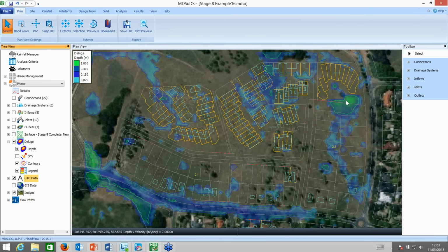So would that be an idea to put something in place like a bioretention area? If there's already some depressions there, we can do a little bit of earthwork landscaping and then maybe benefit from putting something meaningful in there right at source. So we're trying to really slow down the flows. We're trying to provide things right at source across the site and maybe some regional control as well.